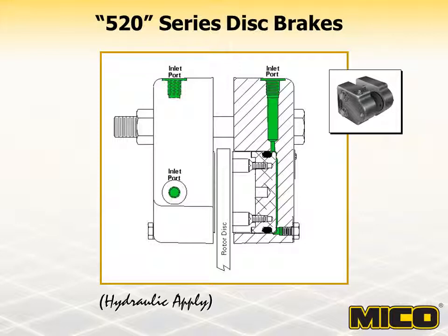The design of this brake allows for use with a disc diameter of 9 inches to unlimited, or a straight rail to provide full lining to the surface contact. The customer must plumb hydraulics to both sides of this brake. It is shown in the static position and operates the same as the 520 brakes in the previous slides.